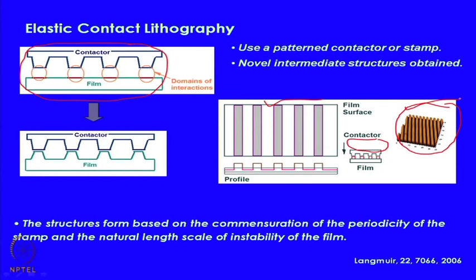So, you are seeing atomic force microscope images in this particular case. At every stage, the patterns were frozen by UV ozone exposure, so that a stiff surface layer appears, and therefore these structures can be made permanent, and then one investigates them. The critical question one can ask is, looking at a structure like this, how do you determine whether it is a positive replica or a negative replica?